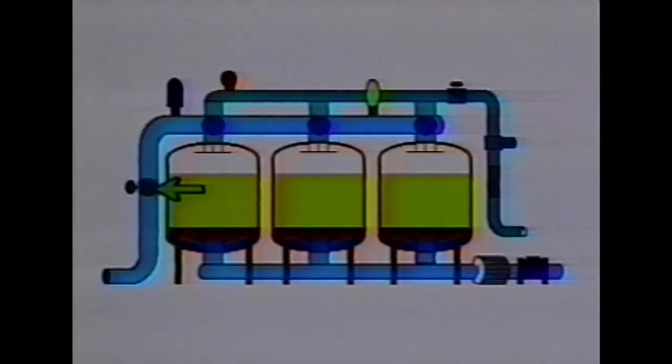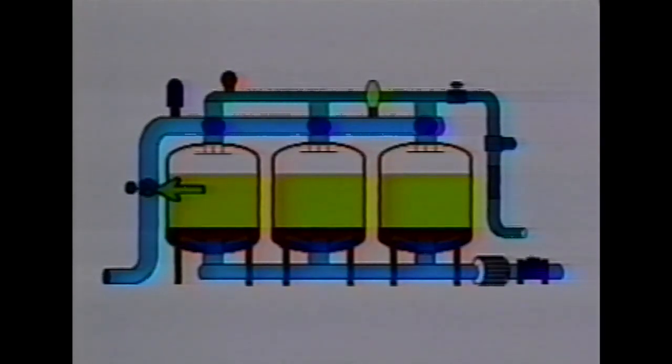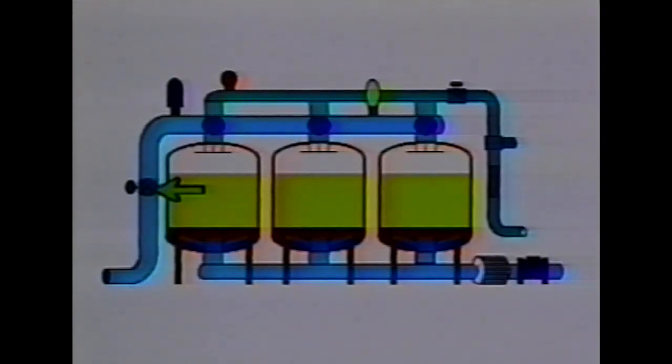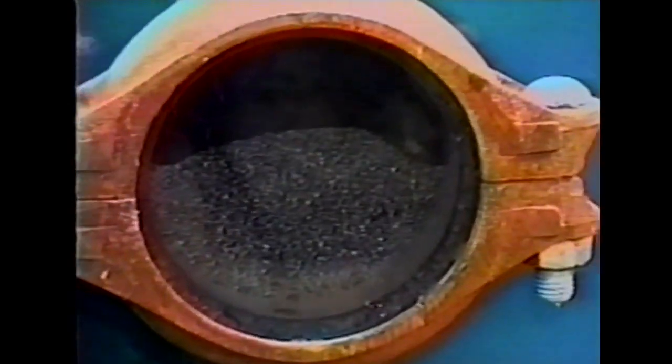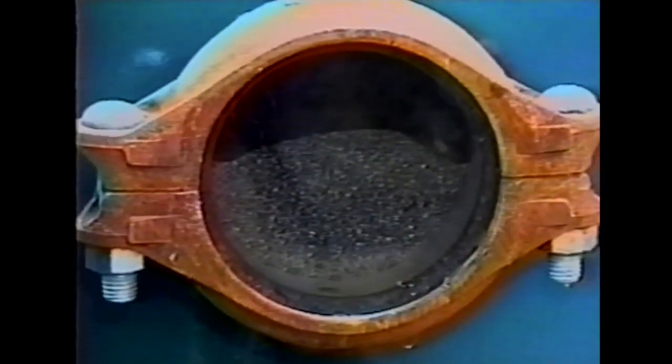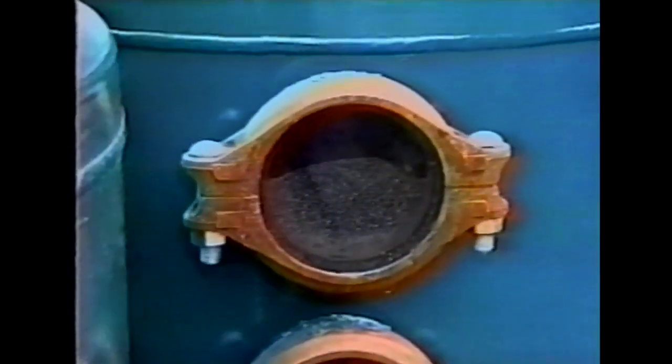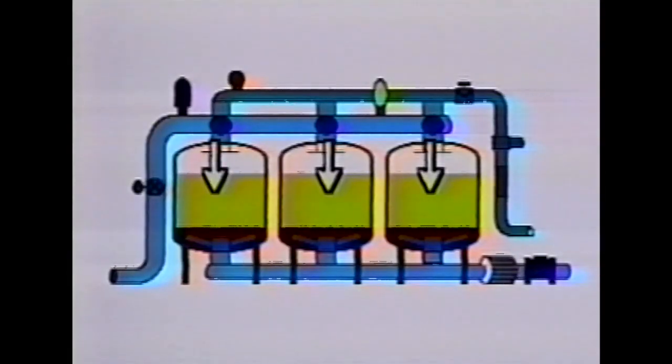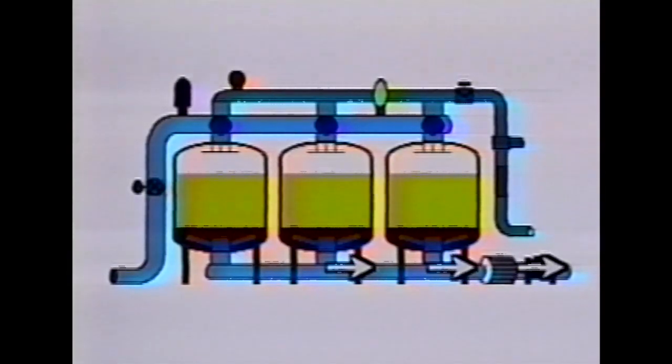A rinse valve is necessary upstream of the filters for some installations. The rinse valve is only used during the initial cleaning and backflushing of the filters. Media and gravel, when purchased, often have a high percentage of fine particles which could pass through the tank underdrains and into the irrigation system. It is necessary to clean the media and remove those fine particles before irrigation water is allowed to pass from the media tanks and into the irrigation system.